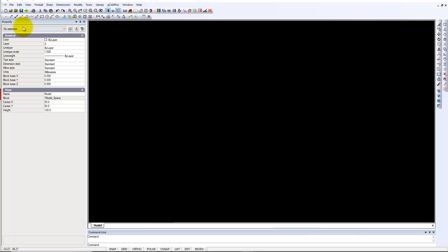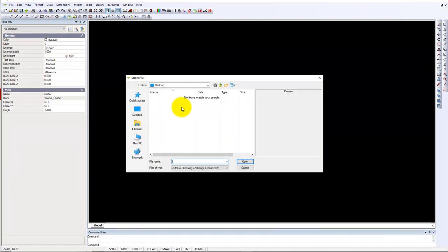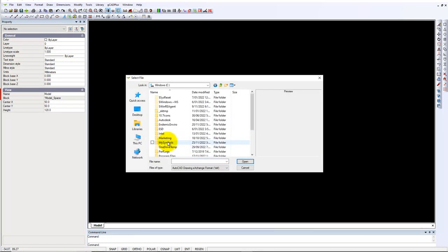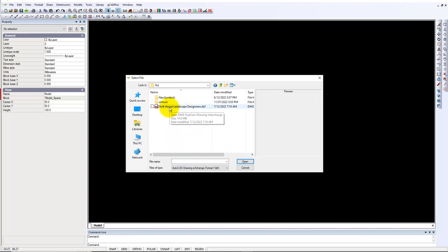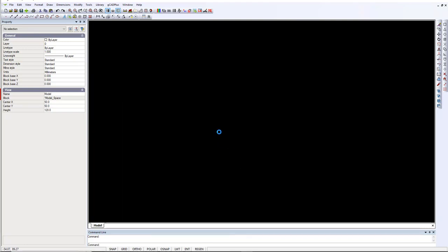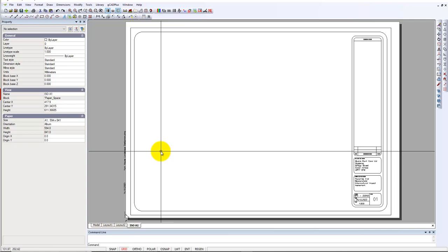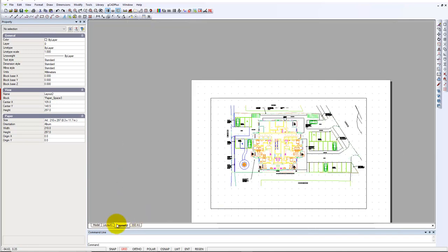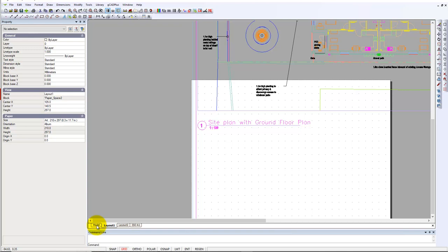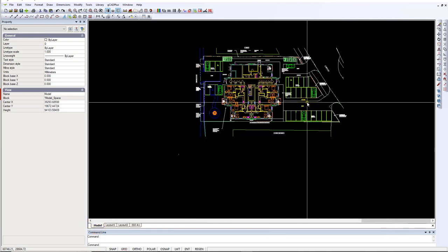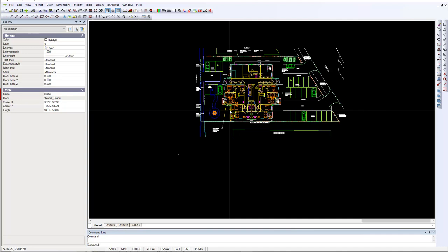And what I'm going to do is to use a tool that we've developed called DXF Tools In. We're going to suck in that DXF file, which was in the temp layer and in the out folder, and here we are, it's called York House, so we'll import it, and I'll zoom extents. So the layouts come in and so on. What I'm going to do is go to the model. So here's the drawing. It's currently called No Name.